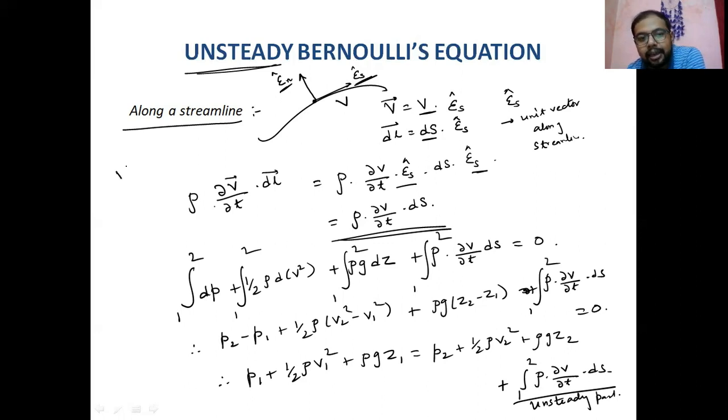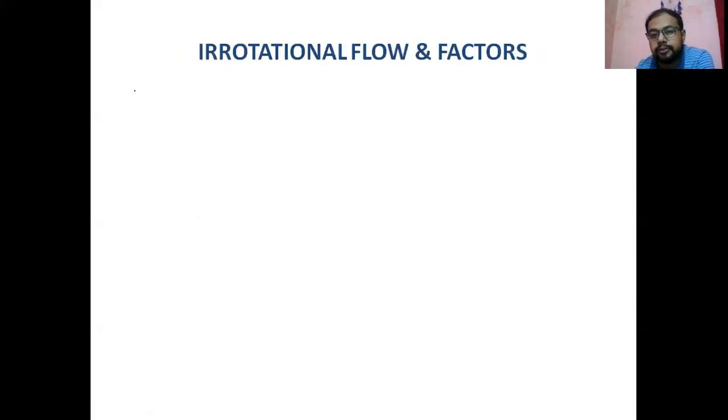So it seems like a one-dimensional velocity at any instant, which is easier. A two-dimensional case can be reduced to a one-dimensional problem if we use the streamline coordinate. That is the advantage. So first we take along the streamline. If it is an irrotational flow, then what will happen?